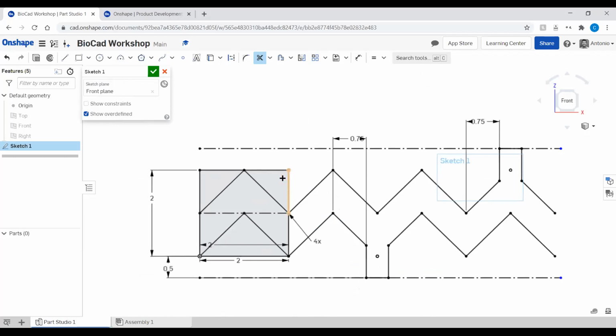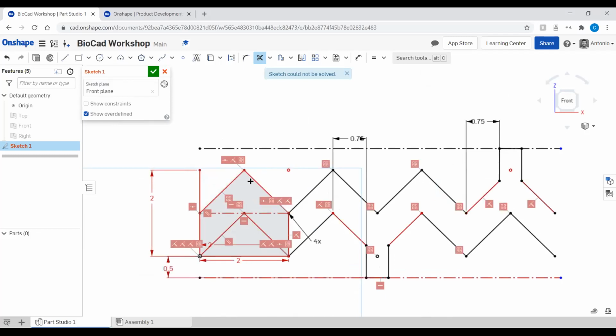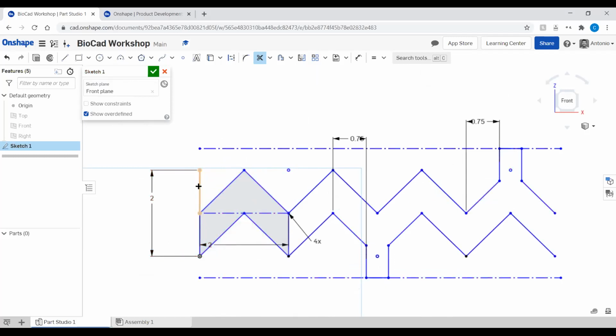And you can also start deleting some of the box because we're not going to need that anymore. You should see that it starts to turn red because things are unconstrained. Sweet. So now I've got this whole entire open piece right there. So what we're going to do now is, before we mirror it across, this is still sort of half of our unit. I'm going to delete this glass meshes that were completely open there. Everything should be blue, nothing should be filled in.